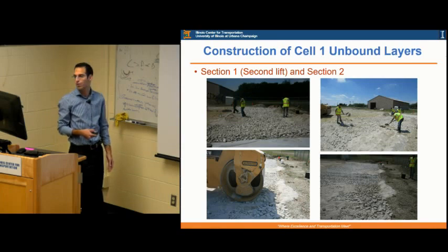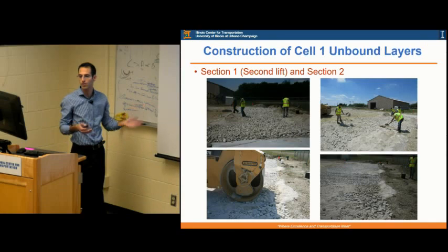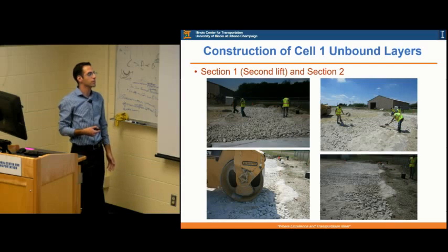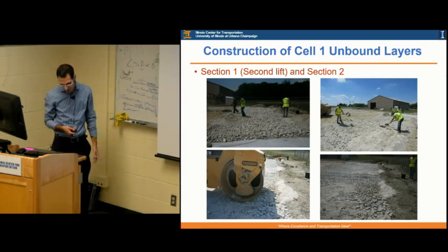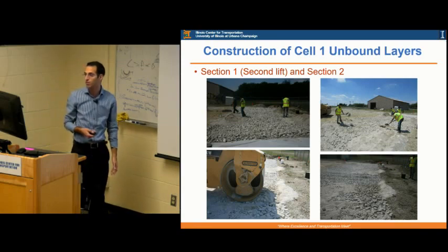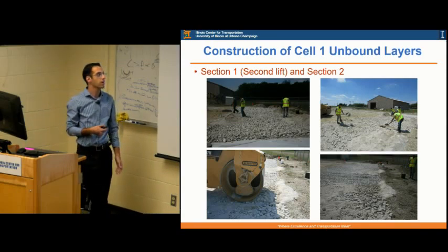We were a team of 4 PhD students, 2 professors, and postdocs even, just shoveling on the hottest day that summer quarry byproducts inside the large rocks. And the amount that we shoveled is actually 16 tons of quarry byproducts inside those large rocks. And it was working successfully this time because the application was slower, so we were manually shoveling it and then using a stronger vibration to do it, and it was giving us similar results to what we had in the lab.